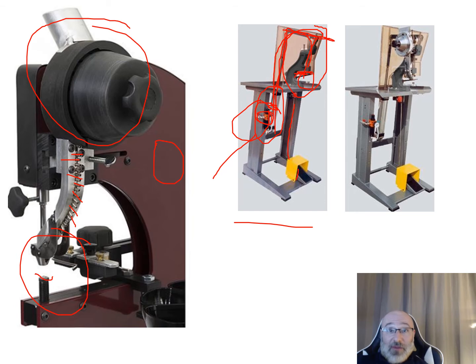So this is great for a couple different reasons. One, it doesn't take much force down here on your foot pedal. Two, you've pneumatically set this to the right pressure every time, and you can have a list. Okay, I'm dealing with leather today, I want it at this. Now I'm riveting plastic, I want it at this. Now I'm riveting to metal, I want it at this pressure setting.